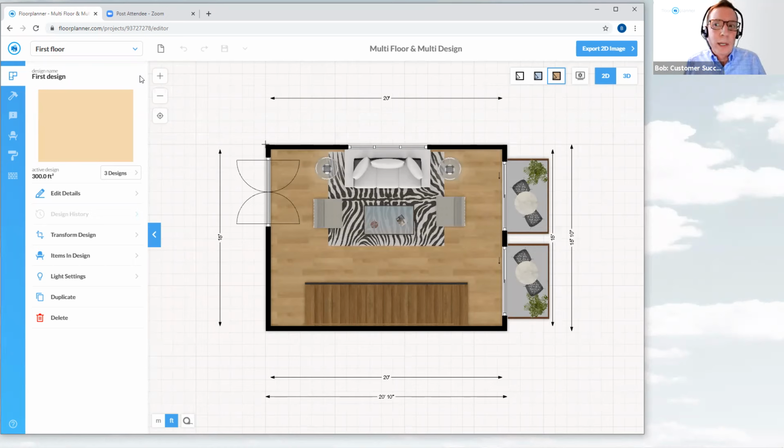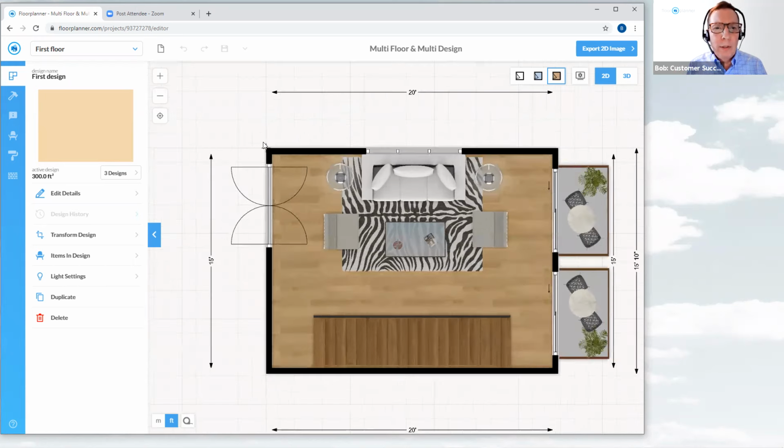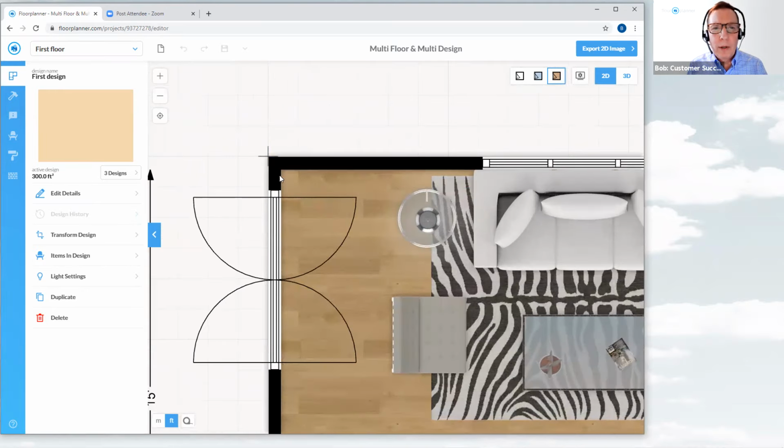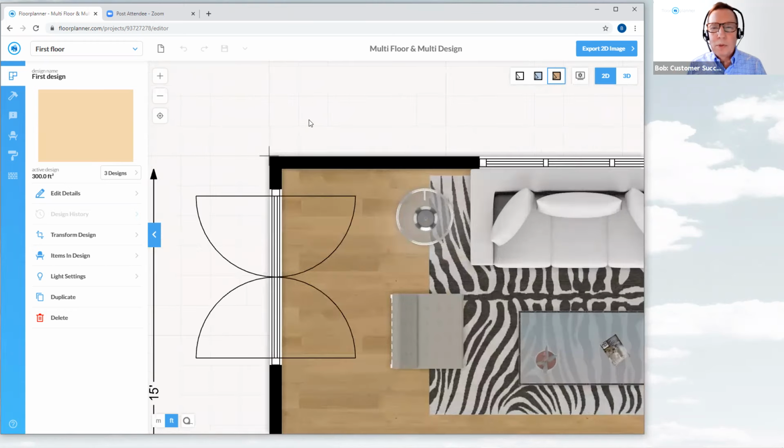But for right now, we just have one floor with multiple designs. So let's go ahead and place a copy of this above it as a second floor. Now, you have in here this crosshair. This one crosshair point shows on your graph paper. You've probably seen that out there before. That's an origin point. That same point is a reference point for every floor of your building.